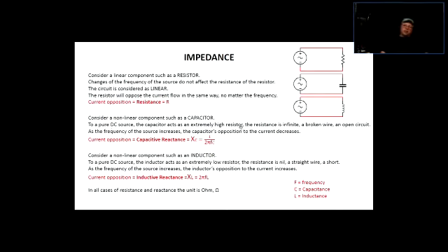What is another example of an extremely high resistor when you have two terminals? All right. Well, the air. The space between them is also an extremely high resistor. Between here and here, there is a resistor in the form of air. So that's the same thing. So to DC, the capacitor acts as an open circuit. Also nothing new so far. Right? The resistance is infinite. A broken wire, an open circuit.